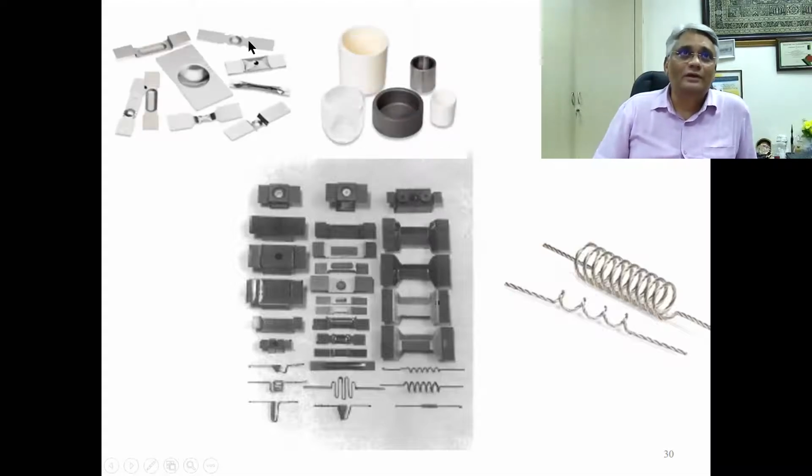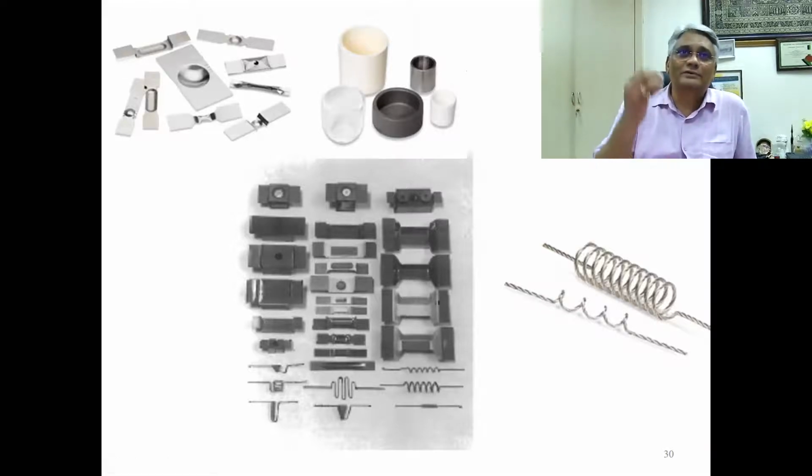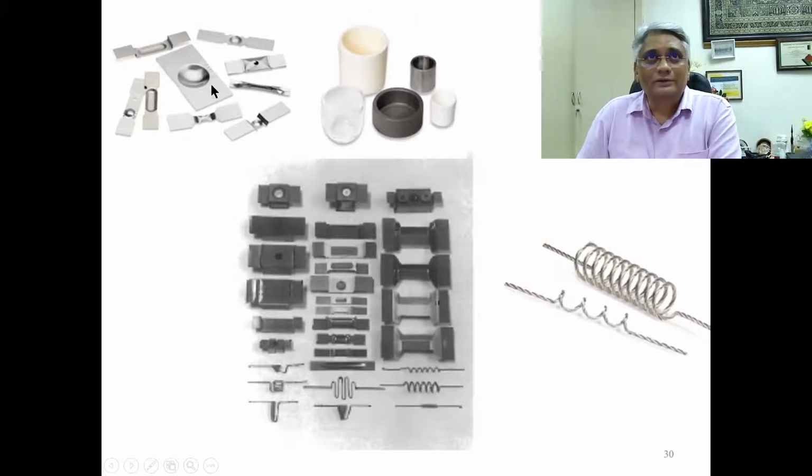Yeah, you see that? These are more sophisticated ways of making these boats. You see how small it is? I can use a small piece of 1 gram of gold, and then I can create vaporization leading to the coating of our choice, right? And these are all small depressions that are created in these molybdenum and tantalum boats. Some of these are expensive, but they can also be reused. For larger quantities, you can go for this type of crucibles.